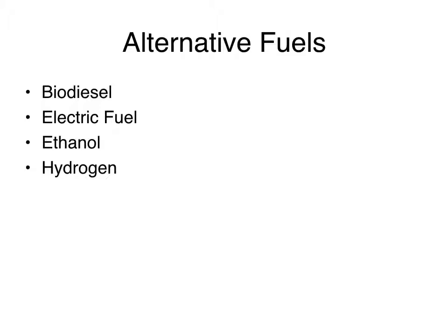Hydrogen. Hydrogen gas can power combustion engines and fuel cell vehicles. And this is electricity generated from the reaction of hydrogen fuel and oxygen from the air that provides fuel cells with clean, quiet power. The only emissions are pure water and heat. And while this sounds great, the challenge, though, is to safely distribute and store the hydrogen. It's an explosive gas at room temperature. So while we have the mechanism to distribute gasoline, we certainly do not have the infrastructure to distribute hydrogen.